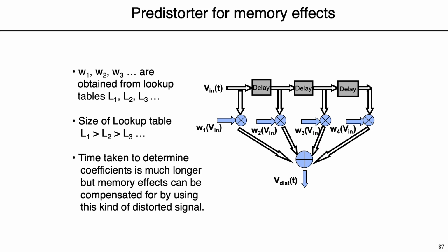For example, you can make a tap delay line structure with nonlinearity that has various elements of the input signal delayed and then added with different weights and different nonlinearities, which allows you to produce that kind of input, call it a generalized nonlinear memory predistortion, that you put into the amplifier, and that can produce the output that you want. That would give you the correction method.